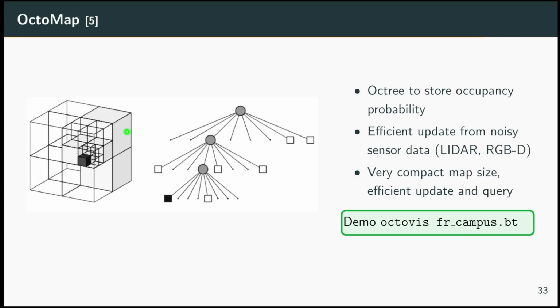One is the data structure called the octomap. It allows you to take LiDAR or RGBD data as input, and you create what is known as an octree, which is a very memory efficient and lookup efficient way of getting convex obstacles, because each of these regions is really just a cube, which is convex by design, and it also means you know the exact position, just generated from raw sensor data.